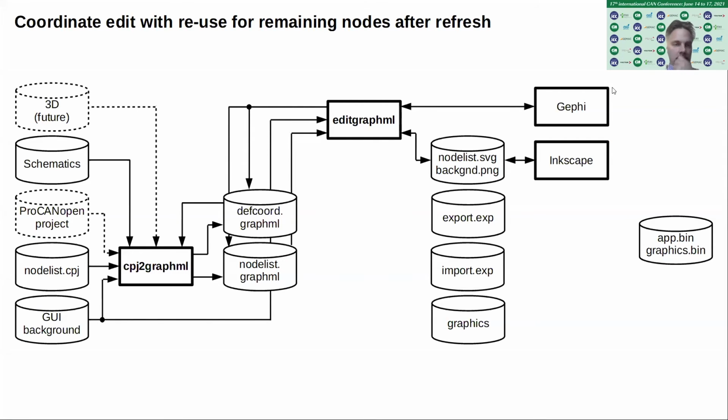And then, of course, because a CANopen project is not capable of carrying screen coordinates and other kinds of location information, in one research project we developed a GraphML-based system description file, which can efficiently carry that information. And the good thing about that file format is that it's intended to describe graphs, which means nodes and interconnections between them. That was a perfect match with CANopen networks.